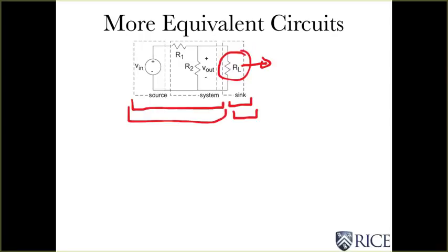You may say, well, the voltage V out is across both the RL and across our original R2, but in reality, it's really across the parallel combination. Well, that changes the resistance, so you should expect there might be at least the possibility of some change in V out. So I want to explore that.